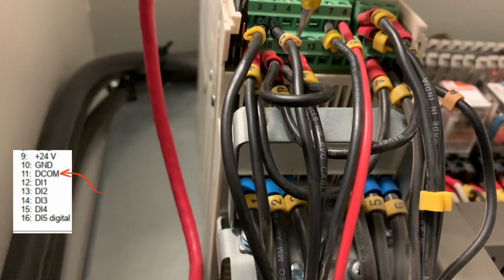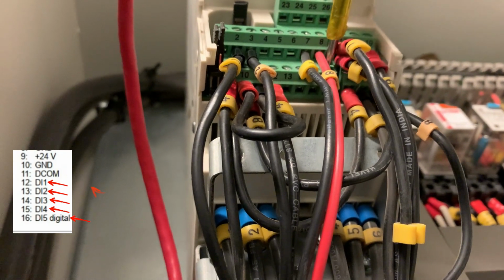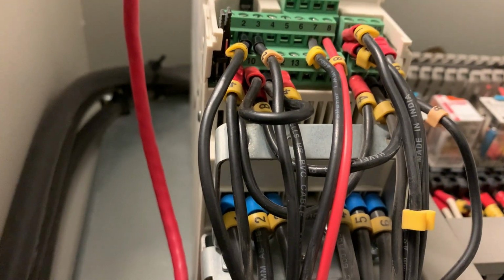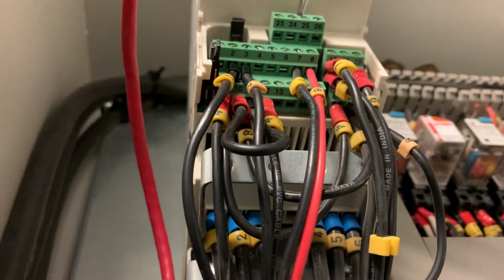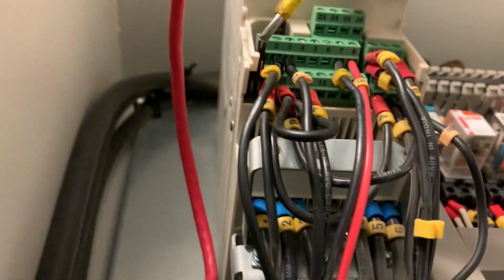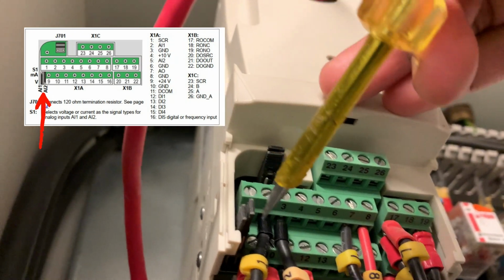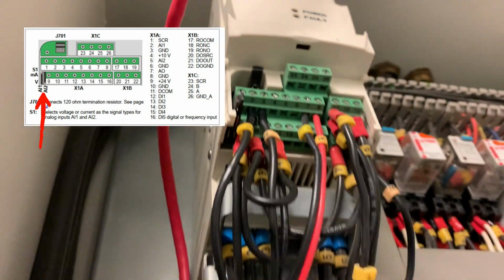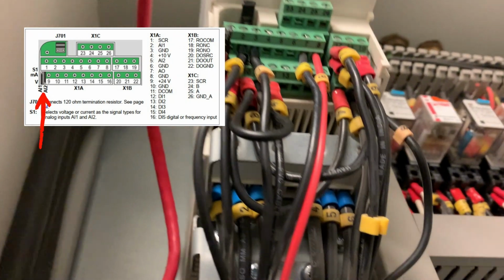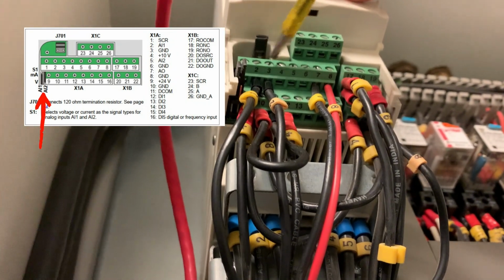These digital pins are, there are 5 digital pins: 12, 13, 14, 15 and 16. Okay, so this is the terminal details. I already explained these terminal details in the manual video in part 1, and also these two, as you can see, these two are for a dip switch, through which you can decide whether you want 0 to 10 volt as an input or 0 to 20 milliamps for the analog input.